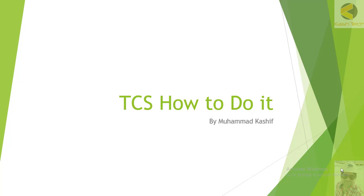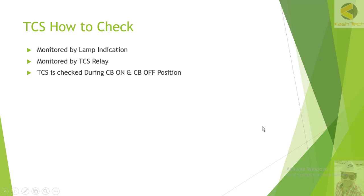Welcome guys. Now in this section we will see how we can do the trip circuit supervision. So trip circuit supervision can be monitored or checked by two methods. Method number one is using a lamp, and method number two is by using a trip circuit relay. So using a lamp is basically a very old technique, but nowadays trip circuit relays are used most commonly.